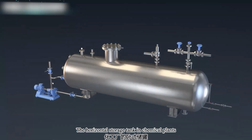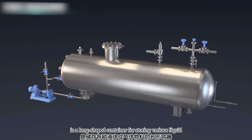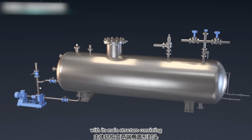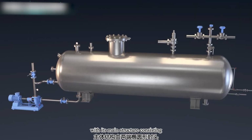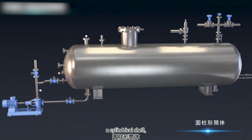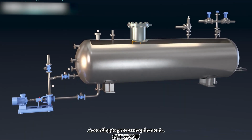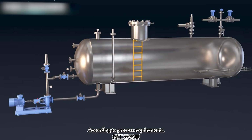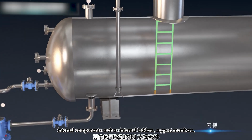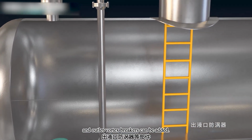The horizontal storage tank in chemical plants is a long-shaped container for storing various liquid or gaseous materials, with its main structure consisting of elliptical heads at both ends, a cylindrical shell, movable saddle supports, and a manhole. According to process requirements, internal components such as internal ladders, support members, and outlet vortex breakers can be added.